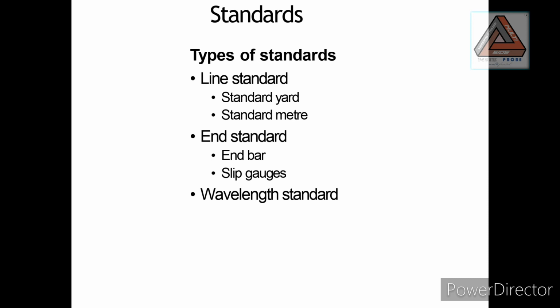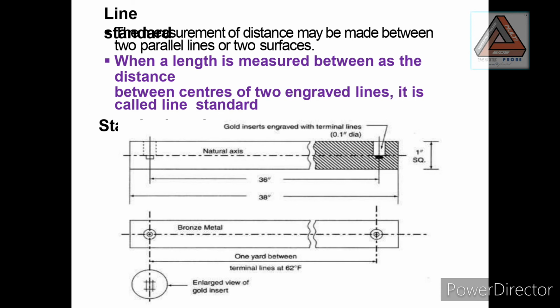Factors affecting the standard of measurement. What are the factors affecting the standard of measurement? Coefficient of thermal expansion, elastic properties of a material, stability with time, calibration interval, geometric compatibility. Factors affecting the workpiece to be measured: coefficient of thermal expansion of material, elastic properties of a material, cleanliness, surface finish, surface defects such as scratches, waviness, adequate datum on the workpiece, thermal equalization. These are all the factors affecting the workpiece.